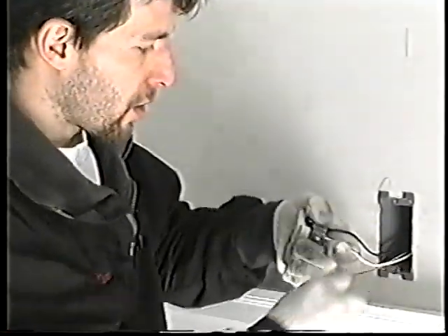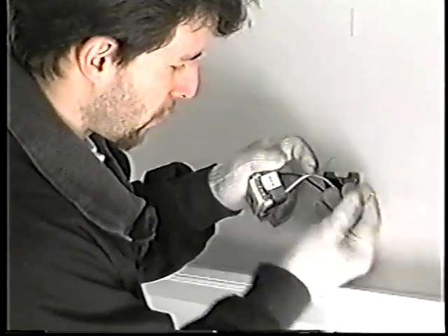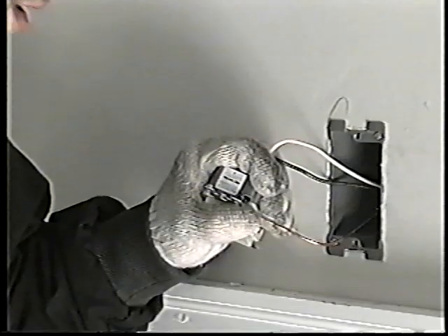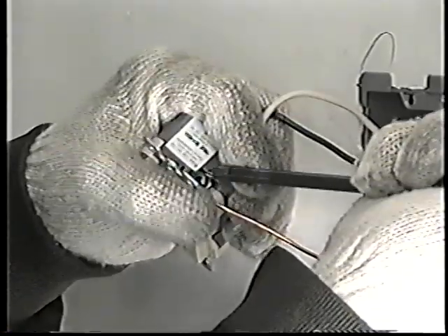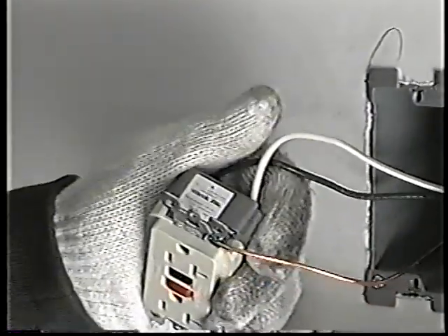Okay. And the last step you have to do also with a GFI is you have to put the ground wire on, which every ground screw is green. And if there is no ground screw, then it'll be designated by some other means. It'll say either equipment ground or grounding or some other way. Almost every switch and every plug has a ground attachment to it. The ground is put there for your safety in case something was to ever happen.